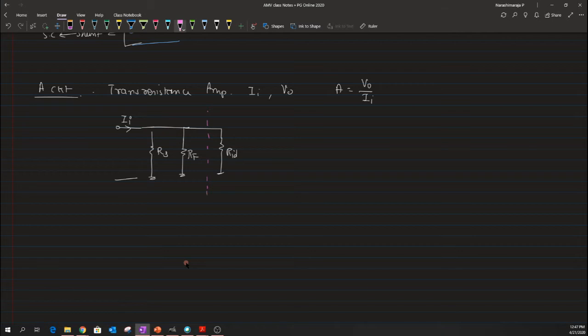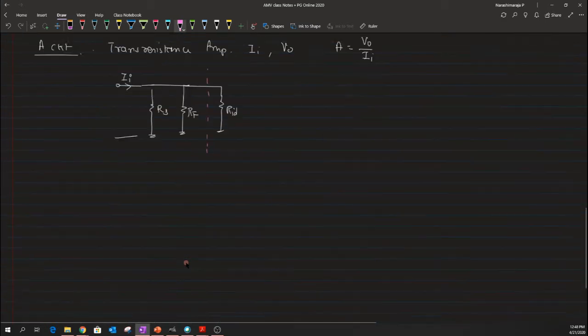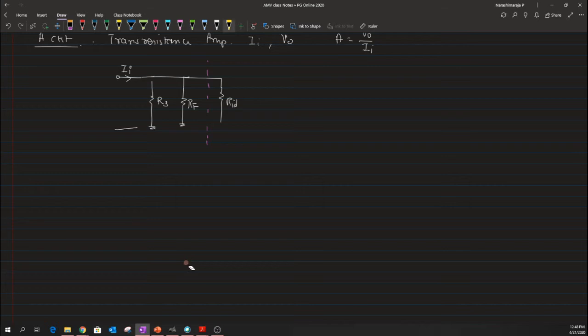We know that the positive terminal of this op amp is directly connected to ground, and we have the positive here and a negative here. We will remember this such that while computing the gain, the type of op amp configuration that we have used is an inverting amplifier configuration. So now what we have is a kind of voltage amplifier. The op amp, as I said in the last class, is always taken as a voltage amplifier,